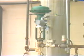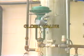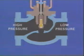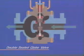The most common control valves are globe valves like this one. Let's take a look inside. This design is called a single-seated globe valve. These valves are often used in smaller sizes only. That's because the differential pressure across the valve plug causes an unbalanced force to act on the valve stem.